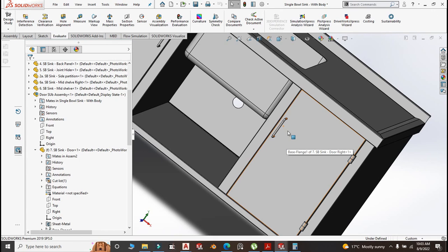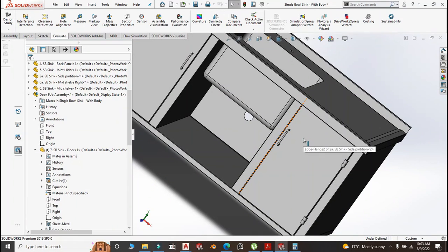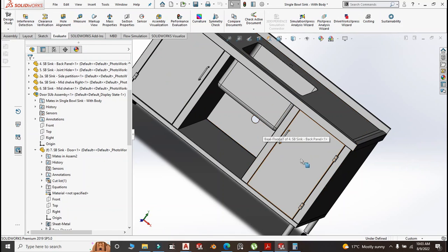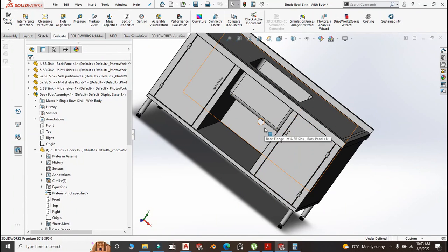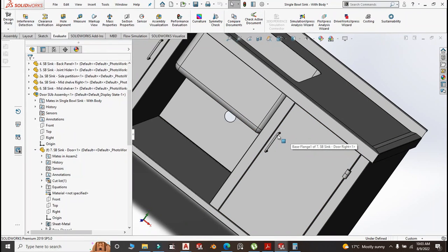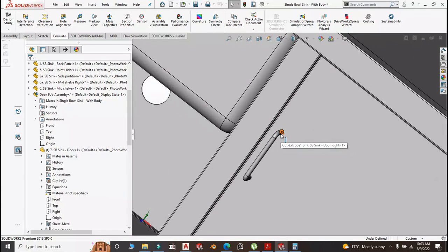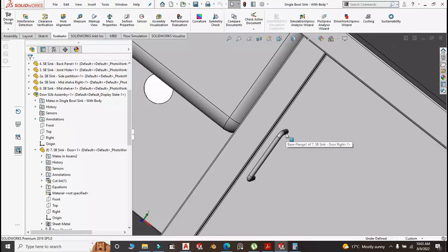Also, before you punch holes, if you're using CNC, I know the guys that don't have CNC normally do these holes manually and they do them later after they have done the assembly. But if you are using CNC and you want, when you are feeding the program to the machine, to cut this hole as you cut the other parts, please make sure you confirm these heights, right? And also confirm the handle that you're going to be using, the diameter of the screw that you intend to use.